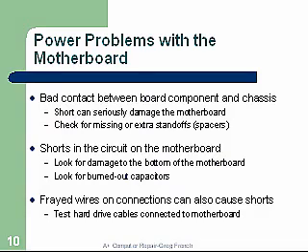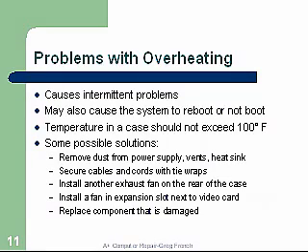Problems with overheating cause intermittent problems also. It may also cause the system to reboot or not boot. Temperatures in the case should not exceed 100 degrees Fahrenheit. If they do, you'll find the computer shuts down or starts operating erratically.